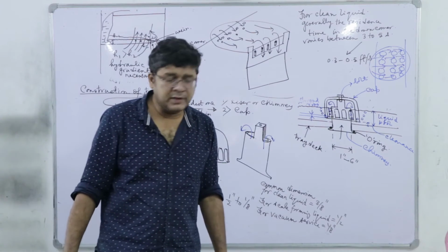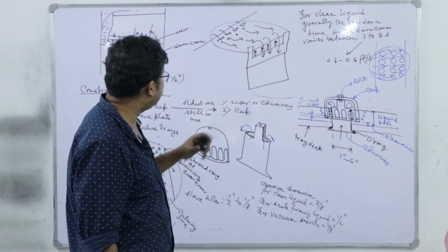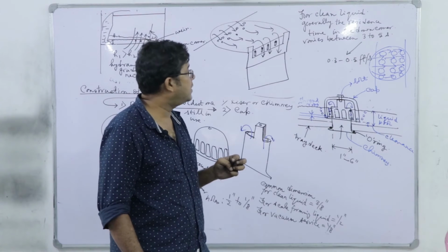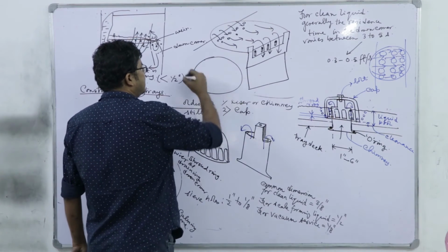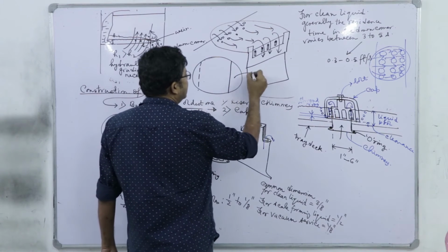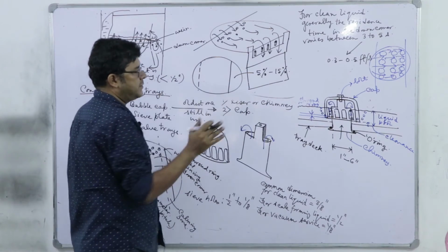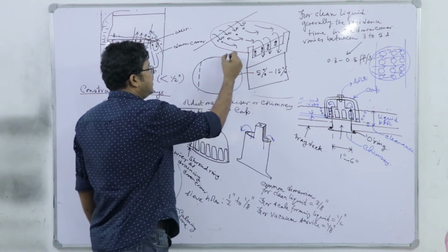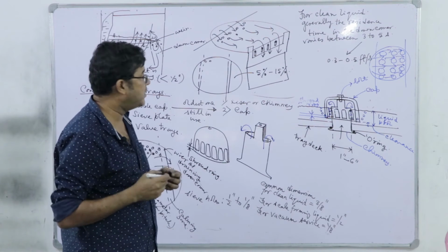Now, in relation to this downcomer weir and the weir height and hydraulic gradient, we must discuss a non-ideality called flooding in packed column. But before we go into that flooding, let me tell you that here we have the incoming downcomer projected area and outgoing downcomer projected area. This individual downcomer area varies from 5 to 15%. So, on both sides we have projected areas which are to be sealed. There should not be any sieve or bubble cap here. And additionally we have this calming zone, and after a certain clearance we should drill the sieve, if I am using sieve, or place the bubble cap.